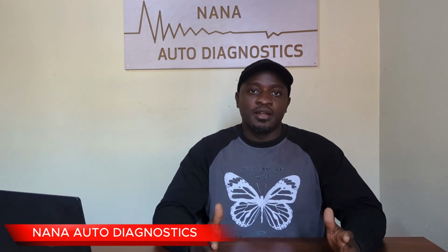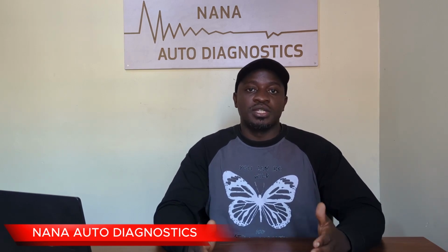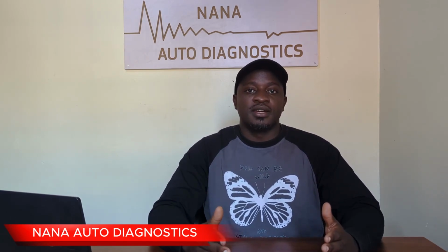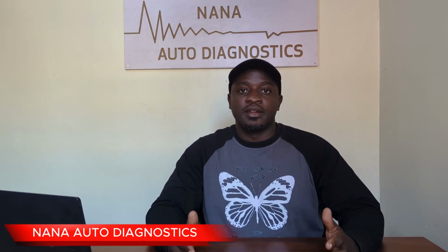So if you're working with Ford cars between 2005 through 2007, you need to verify with your wiring diagrams to see what exactly you're dealing with, because you may have some models using PWM and others using K-line.